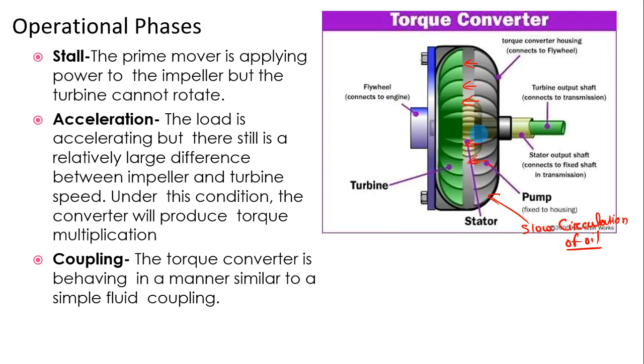Therefore the oil returns back to the pump with almost no loss of velocity except due to friction. The oil goes there but cannot rotate the turbine, so since it is all inside the same housing, it comes back again towards the pump. So the net effect of the redirection of flow is to increase the pump output, and the pump output under this condition is the output velocity that is created by the engine torque.